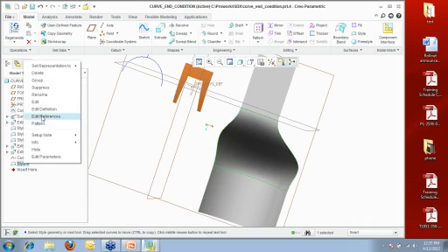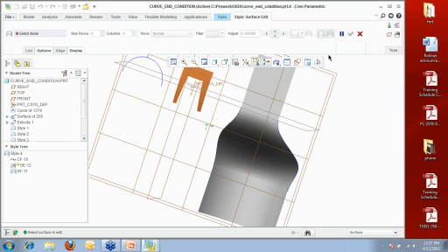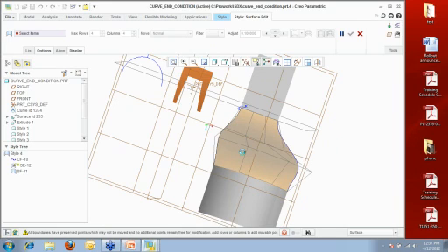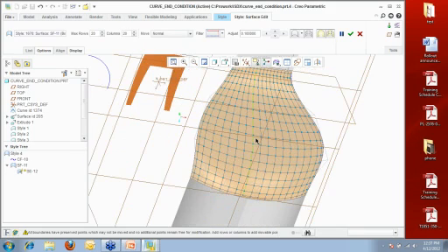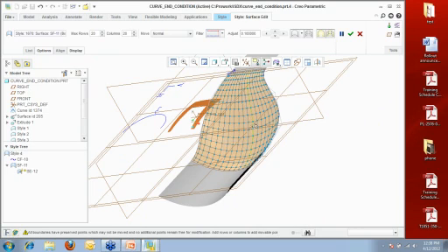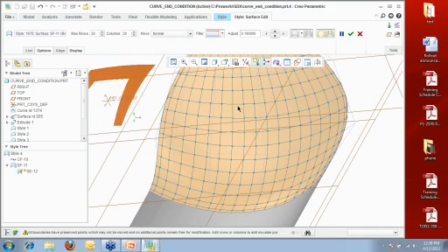If I come back into this style tool, we've talked a lot about editing of curves. I can do surface edits also. And then what really makes this cool here, okay, is I can come in and now I want to edit this surface. Let's say we want 20 rows of these. And what it does is create this grid now in the middle of this, freeform wise. What I can do is come in and say, I want to pick that point, hold the control button, pick this point, there, there, there, get all these points picked.